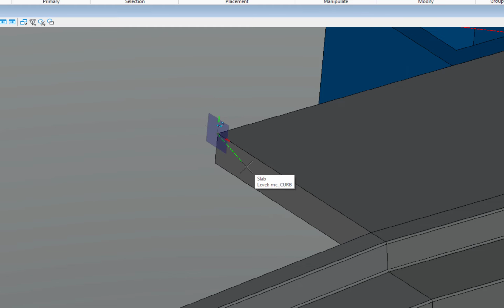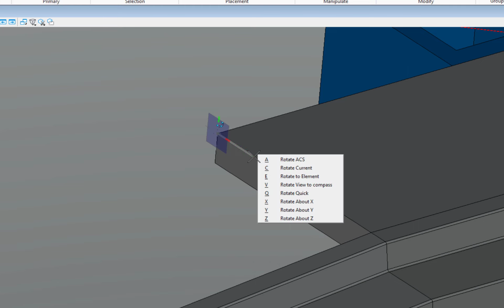The next shortcut we're going to talk about is how do we rotate around any one of the 3 axes. I've already showed you RZ. We'll see that again. The red tick mark, as I indicated before, is the compass's positive X. The green tick mark is the compass's positive Y. We need to rotate the compass, in this case, about the red or x-axis. On my keyboard, I type in RX.